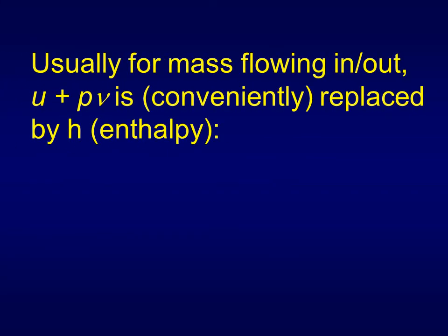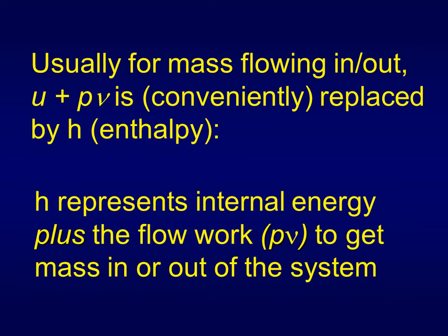Now, again, I mentioned just now that U plus PV is replaced by enthalpy. And so we can say that H represents the internal energy plus the flow work to get the mass in or out of the system. So I like to think of H as the stored energy of a moving mass, where the mass is moving into or out of a system.